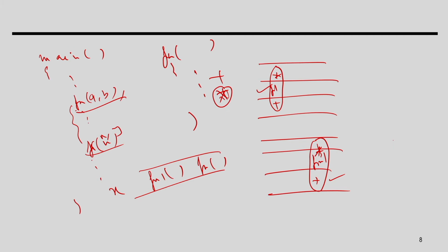I can take one copy and share it with other operations. Suppose an addition operation is happening here, I can use one adder to execute this addition, this addition, and this addition, because they are all non-overlapping. So, the summary of this discussion is, if we have multiple calls and their scheduled times are non-overlapping, it is just like a flattened sequence graph, similar to the sequence graph corresponding to a basic block.